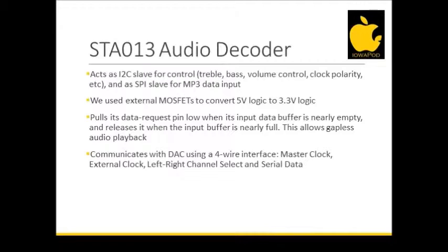However, this chip does not just work when connected to power. Before being used, this chip needs to be configured. To do this, the microcontroller must first perform a series of over 2,000 I2C register writes to initialize the chip before it will function correctly. For this reason, we decided to store a file with all of the data that needs to be written on the SD card and do the configuration on startup.